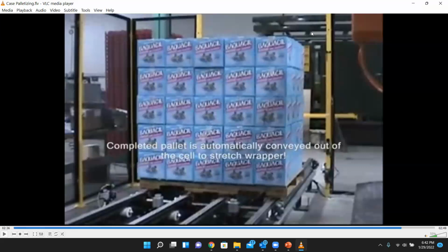If you bring in a second manipulator, you can combine the activities. When one manipulator handles the sheet, halfway you can have the other manipulator bring boxes in, right? So you can speed up the operation, but it becomes a bit complicated. Okay, you have to see whether there's a net advantage or significant advantage of having two manipulators or just one manipulator, depending on your orders. Why do you need a very fast palletizing operation? Do you really need to have a very fast palletizing operation?